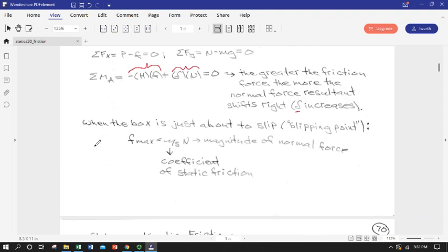And we'll also look at friction angle, so another way of expressing our coefficients of friction. Okay, before we do that, we have to introduce a very important concept that's probably, again, familiar from physics, which is imminent slip. If the box isn't anywhere close to slipping, we really can't say anything about the magnitude of the friction force other than what we can get indirectly from our conditions of equilibrium.